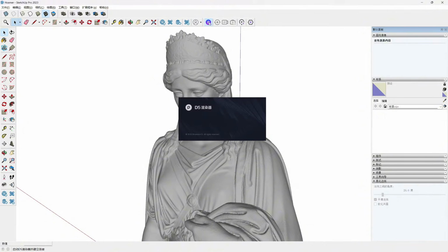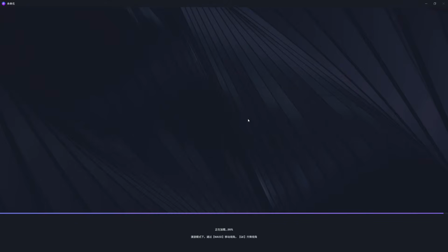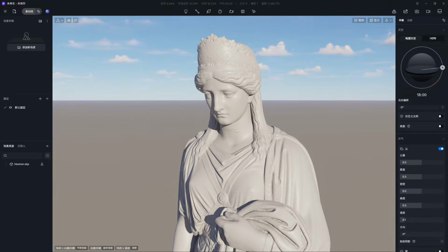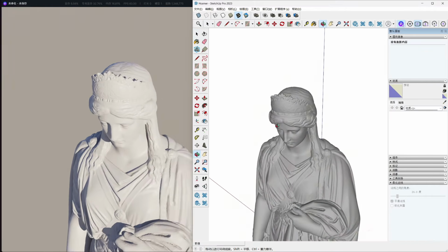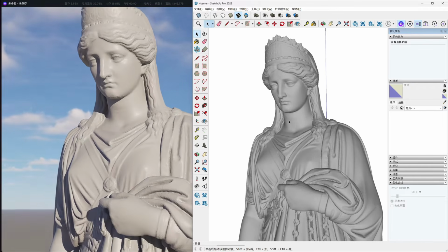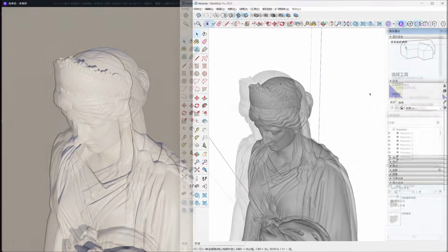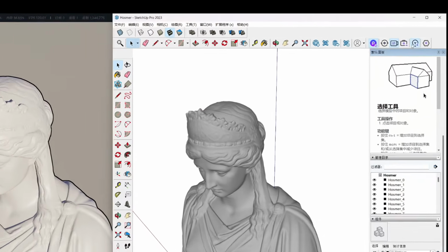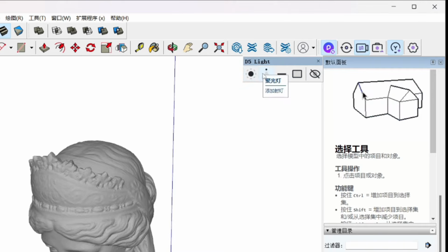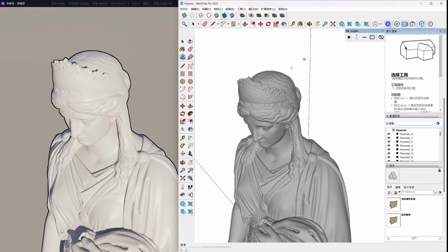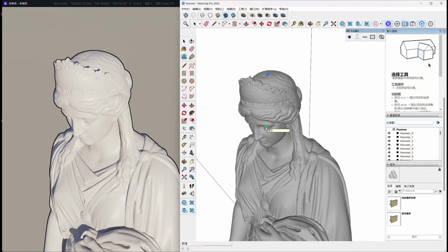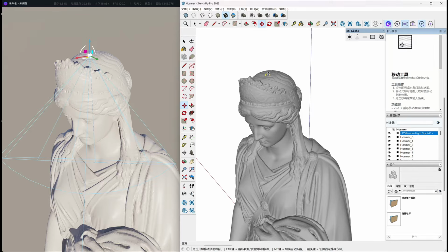Simply click the Start D5 button and select Create a New Project to begin live sync. This brings your models, materials, lights, and cameras directly into D5 without any hassle. The viewports of both SketchUp and D5 are also linked, so you can keep everything on the same page. A lighting designer can add a light source in their modeling software and adjust its position. That light will automatically update in D5.